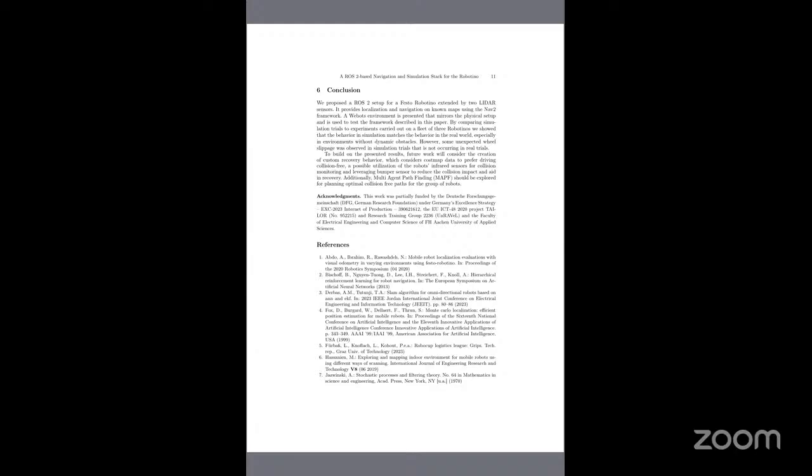In this research, they have prepared a complete ROS2-based navigation system for the Festo Robotino. They used two LiDAR sensors to see the 360-degree environment, and also to find the exact position based on the map and to move autonomously to the required position.